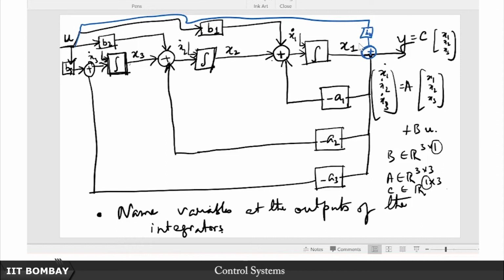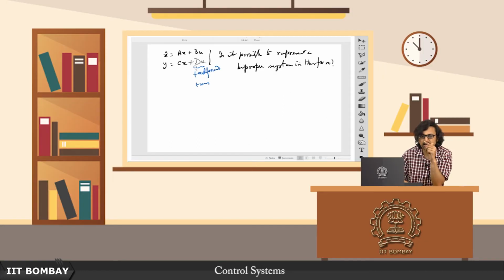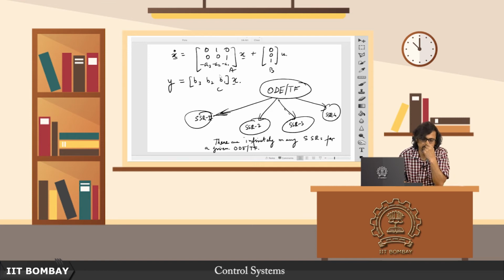So if you have a biproper transfer function, then this x dot is equal to Ax plus Bu and y is equal to Cx is inadequate to capture that, then you also need this so called feed forward term, but again this is a corner case, in most cases you will be dealing with strictly proper transfer functions rather than biproper ones, so at least you are sure that you will not encounter this d, yeah, but anyway it is good to know. But now in this phase variable form also, let me convince you where the difference will be.